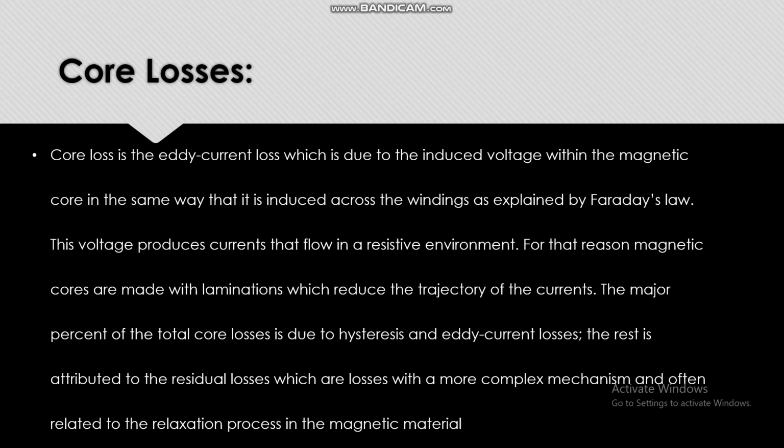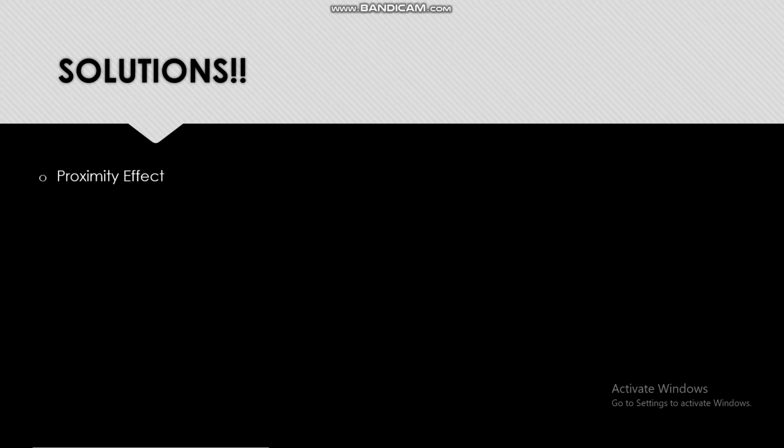The major percent of the total core losses is due to the hysteresis and eddy current losses. The rest is attributed to the residual losses, which are losses with a more complex mechanism and often related to relaxation process in the magnetic material. We'll move on and see if we have some solutions for this. Yes.